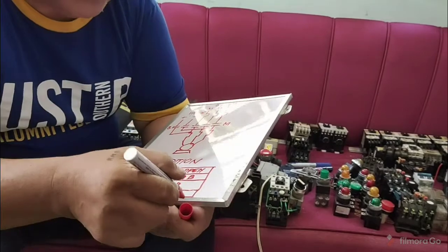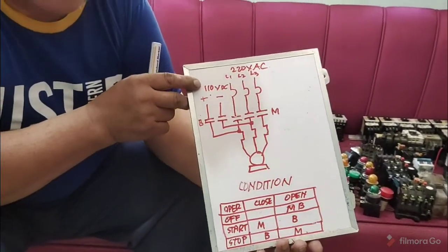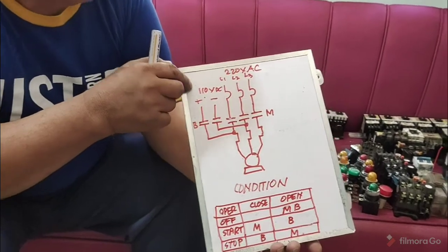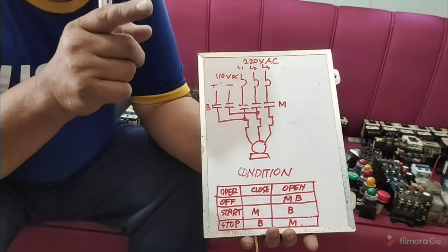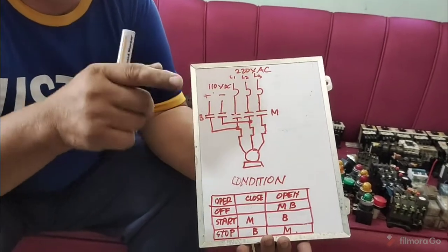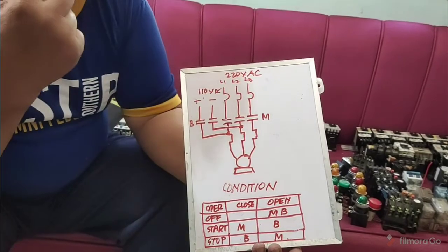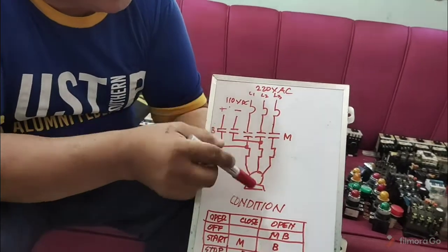Then of course, the voltage here will not be more than 220. Why? Because you will only press the button for a short period of time. When the motor has already stopped, you release your finger immediately from the push button. Then your source is 220 AC.